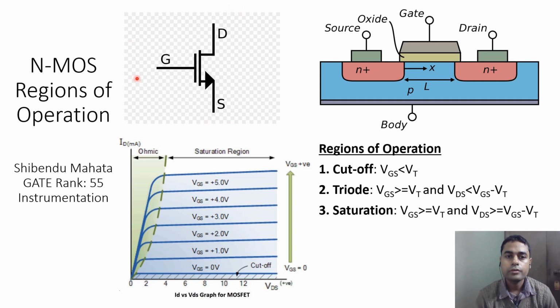So this is the circuit symbol for the N-channel MOSFET, and you will find that the arrow points outward towards the source terminal for this NMOS. This is the gate terminal, here is the drain terminal, and this is the source terminal. And generally the body or the substrate terminal is not shown in a circuit symbol like so.